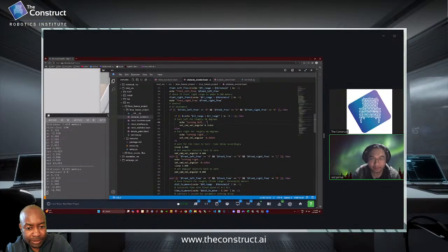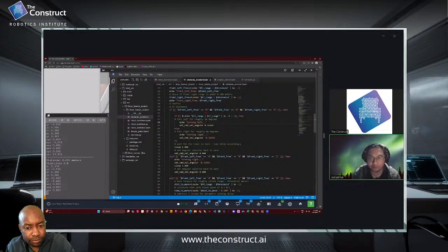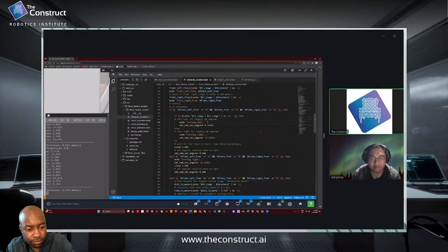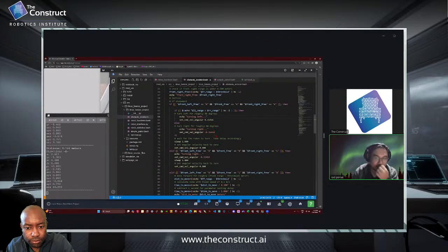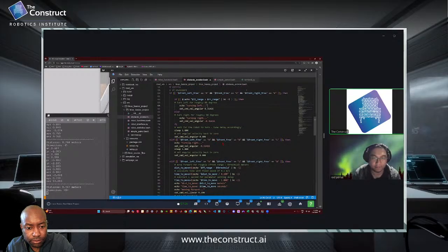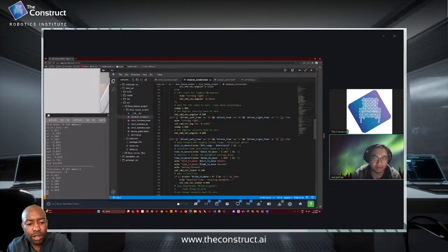For the control algorithm, what I did is, if it says 000, it means everything is black. Inside the if statement, there's another if statement which decides whether to go left or right. This one says LL range. If LL range is greater than R range, which are just left or right, if left is bigger, then turn left, else just turn right. Then sleep, wait for the robot to do the rotating, then stop. How did you choose the sleep time?